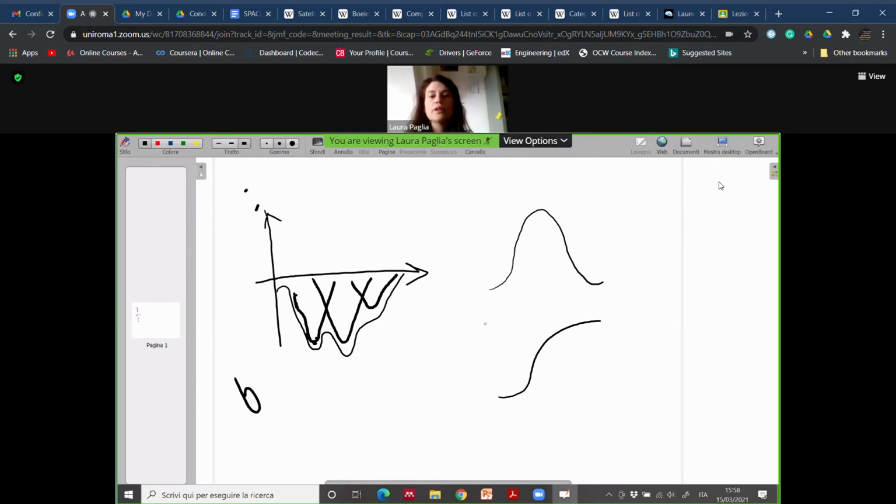And so on. So if I have a multi-step reaction, I can individuate the number of steps of reaction according to the number of the peaks in the DTG curves. In this case, I have to calculate the thermokinetic parameters for each peak. One peak can be approximated with a Gaussian curve. All the Gaussian curves used have to be optimized to rebuild the original DTG curves. Okay.